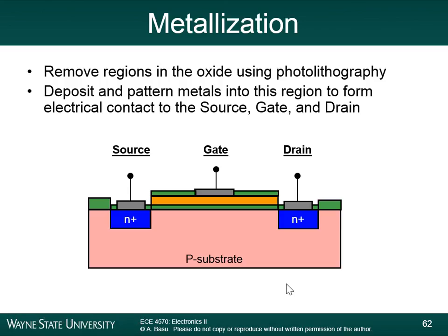Right? The transistors actually have to be connected together to make a working circuit, right? So the transistors are connected to all other ones in various different ways. You can imagine if there's a billion transistors that you have to connect together, very difficult to do that in just one metal layer, right? Because you can't have metal layers that cross over one another. So some of the manufacturing processes nowadays use up to 7 different metal interconnect layers to create the connections between the transistors. And a metal interconnect layer is just a layer of patterned metal and then a layer of insulator. A layer of patterned metal, layer of insulator. So you just keep on going, you stack up the interconnect layers that way.